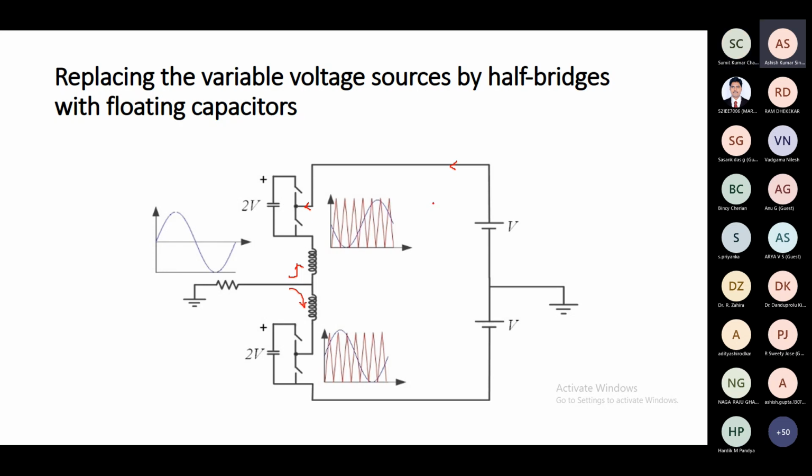When you consider a three-phase system, these AC components of current will circulate within the three phases, because the sum of the three-phase currents is zero. So this DC source will have only the DC component of current. There can be some ripple corresponding to the voltage ripple of these capacitors, not corresponding to the AC component of current. That is going to cancel out within the phases.